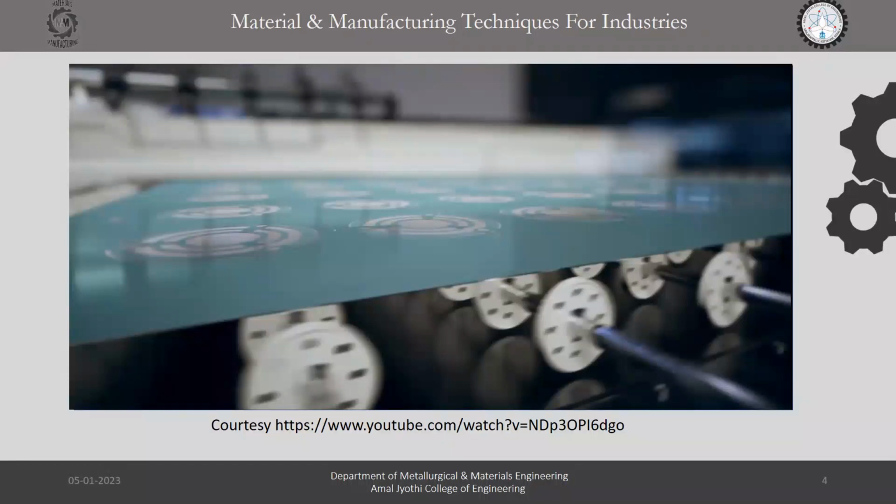Now the third step is etching. This is the process in which the required metal removal takes place. After the masking, we dip the workpiece into a tank filled with the chemical reagent, and the heater and the stirrer are turned on. As soon as the workpiece is dipped, the highly concentrated chemical agent reacts with the non-masked area of the workpiece and dissolves the metal into the agent.